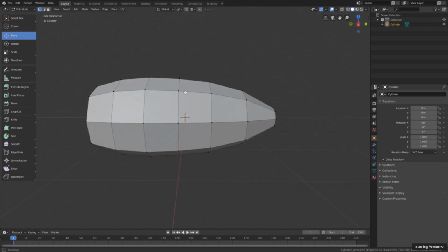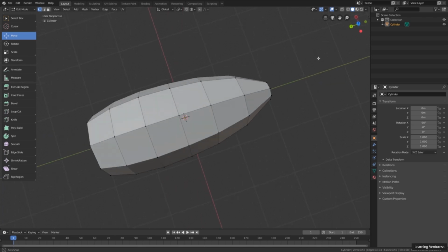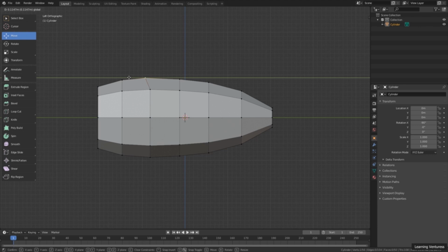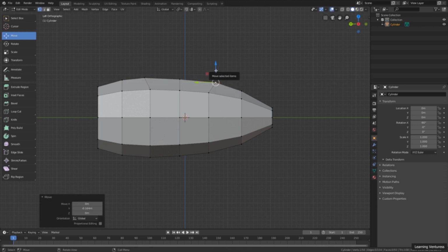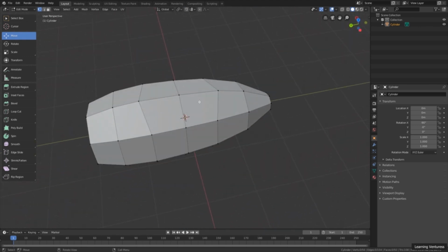And now, as I want to create the cabin using these 4 faces up here, I can position the 3D view in a side view by clicking on this red circle, and I'm going to move this front vertex to the front a bit, just a bit with the Move tool, and these back vertices here a bit backwards, like this. Okay, this way, if we check this form from the upper view, we will see that it's a bit more round, more oval at least.